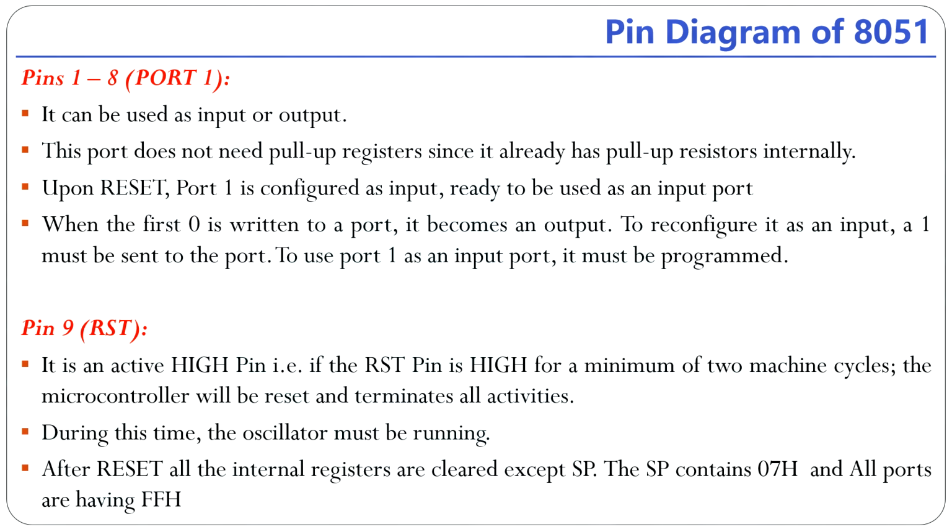First it will terminate all internal activities, whatever it is doing. This is the first operation. Second, and one more important thing, while you are supplying this reset signal to the 8051 microcontroller, the oscillator must be running. Why?